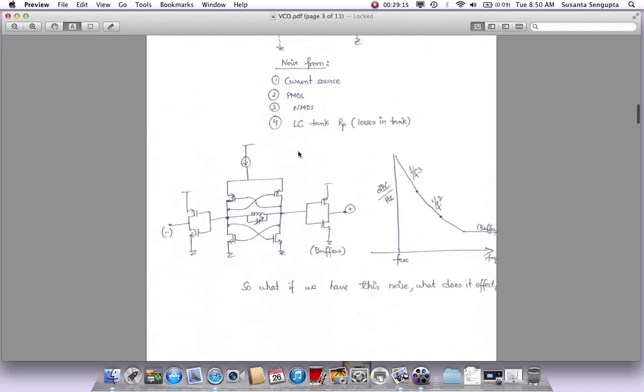Alright, let's see. One other thing I try to add here is, normally when you design a VCO, you will follow it by some buffers, and in many cases the buffers we use are simple inverters like that. We tend to use inverter buffers. So it will take the sine wave and square it up. At the end, we are not really using a sine wave.